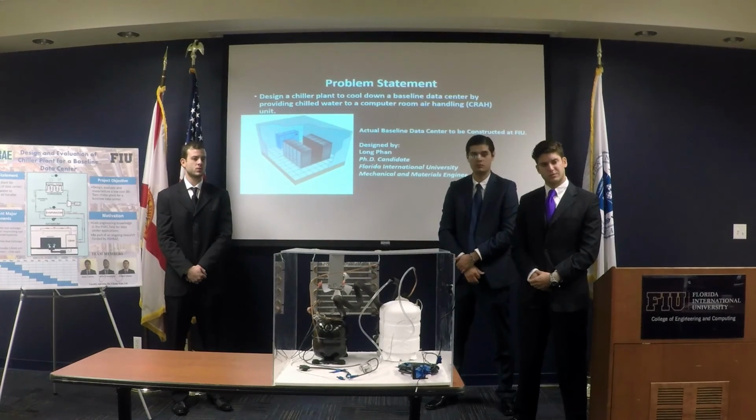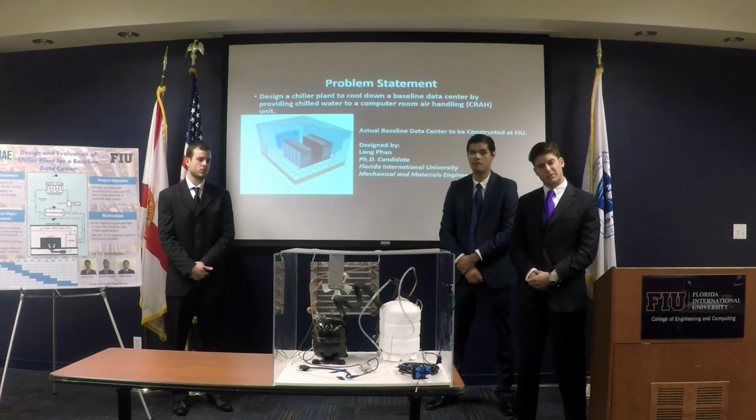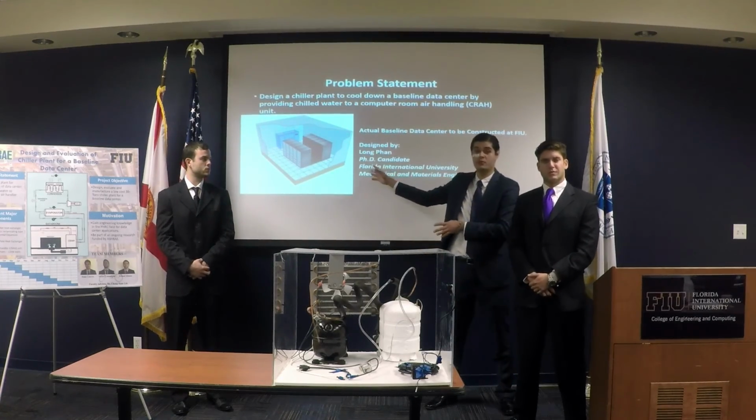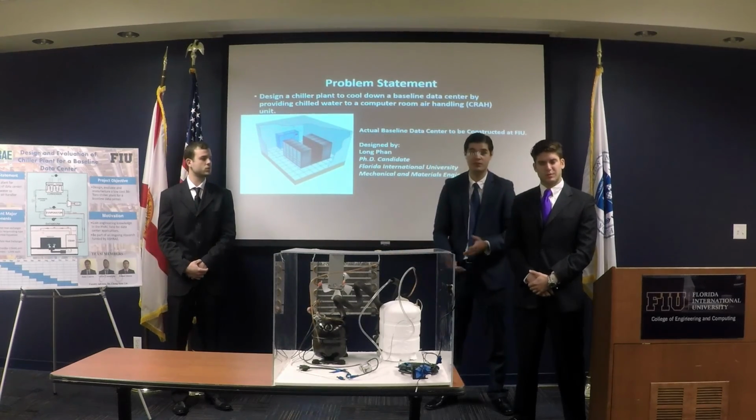But if you get a 70% efficiency rate on your simulation using a 410 system, did you get close to that based on the numbers with the new gas, the 134A, which is a lower pressure and so forth? Actually, when we calculated the coefficient of performance for the full scale, it was 2.7. For this one, it was also 2.7.